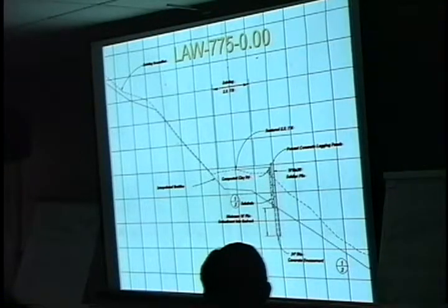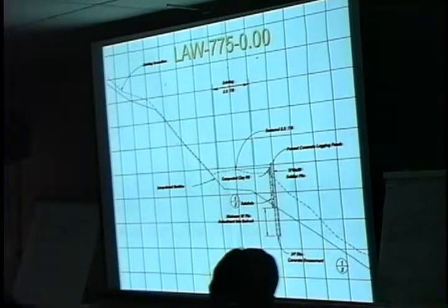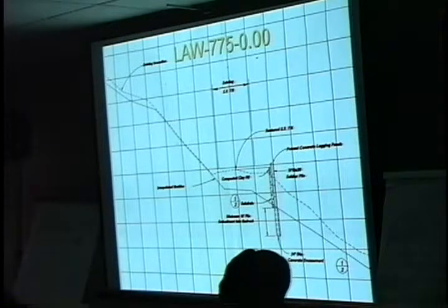The failed soil basically is in here, and this is the roadway in here also. We want to basically keep that soil all in there, and we're going to utilize the rock to do that. And so what we're going to do in this case is socket the H-piling into bedrock and use concrete lagging between the H-piles to restrain this soil.